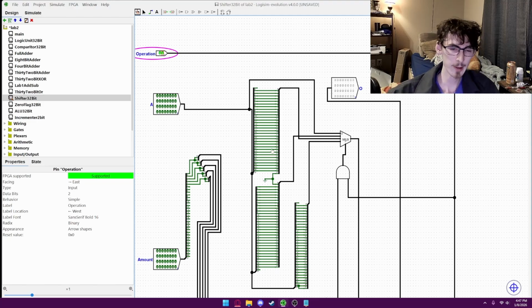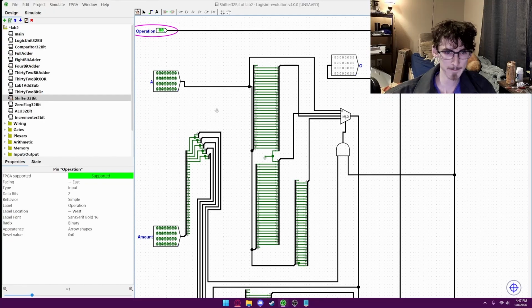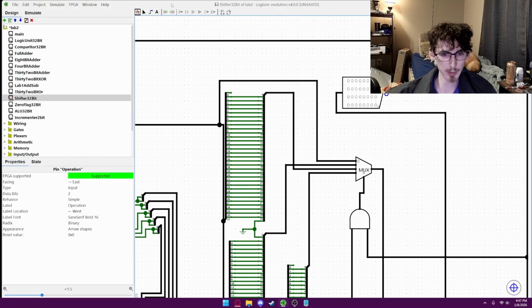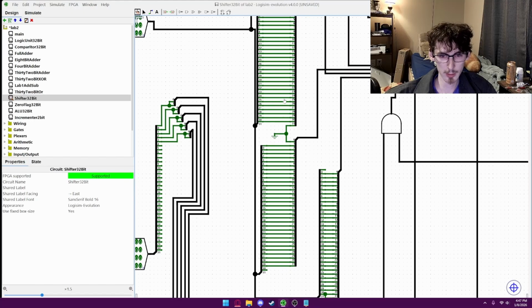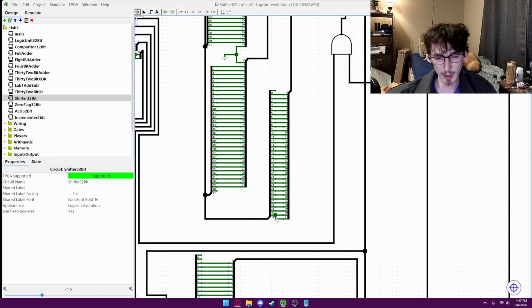How this works. A, this is our input, is passed into our first set of shifters, and this is for 1 bit. Now, as you can see, this is made by a splitter. We split all the pins into the 32 bits, and we just have it offset by 1. And the new bit is grounded for shift left logic and shift right logic. But shift right arithmetic has this pin right here going here, because if this is a signed number, pin 31 would be high, and so we would need to replace any new inputs with a 1 as well.